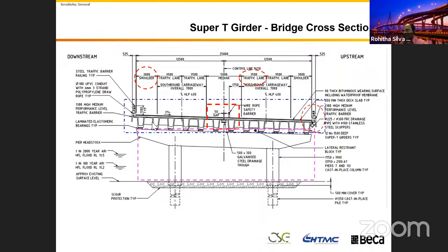And these bridges are then supported on a funny trapezoidal-shaped concrete element, the cross-head. You can see that cross-head and the bridge girder. I'm sorry, I didn't put an enlarged version of this one. There's a small box in there. That box you can see on the other end, we call the, as I mentioned before, elastomeric bearing. The girder is supported on the bearing, and the bearing is sitting on the headstock.